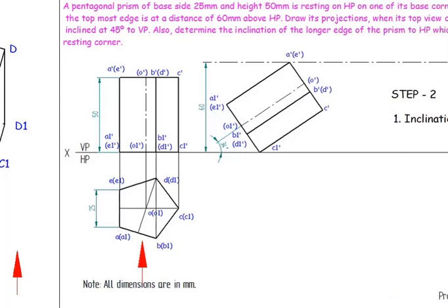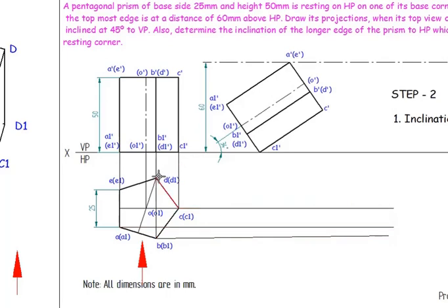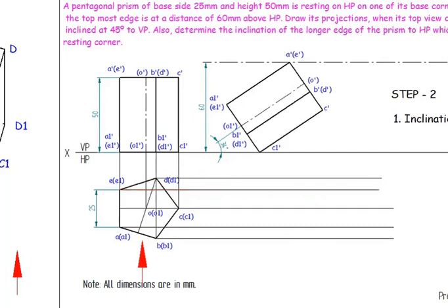So the first thing you need to do is the projections. Start with the letter A. I'm going to draw this A. Again from B I'm going to draw it. Again from C I'll be drawing it. Again going with the D point, I'm going to draw it. I'm going to draw it with E also. So we are going to do the projections from its top view. So I'll go for the line, this is A dash. I'm going to project this line till the point where A is.